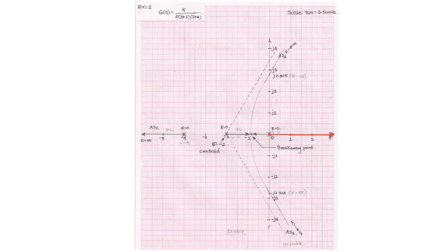And the grid, as I have told you, 1 centimeter is equal to 0.5 units. So here one grid will be equal to 0.5. So this is 0, this is 1, this is 1.5, this is 2. These are all plus. Similarly, because root locus is symmetric about the real axis, whenever you take grid points, take the same for y also. So here plus j of 0.5, j of 1, j of 1.5, j of 2, j of 2.5, j of 3, j of 4, like this. Here on the negative side take minus j1, minus j2, minus j3, minus j4. Put an arrow mark here, then write plus jω if you want.